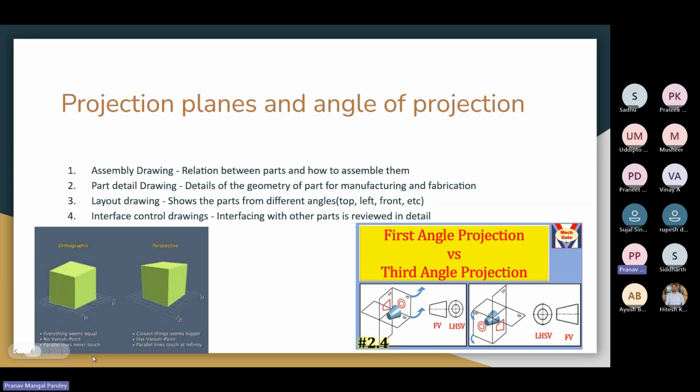This is normally not that much required, but sometimes even a uniform cube might not look like a cube. It might look deviated. For example, here you can see this edge looks like a deviated angle. So in those cases, make sure to check whether you are looking at the orthographic or the perspective view of the body.